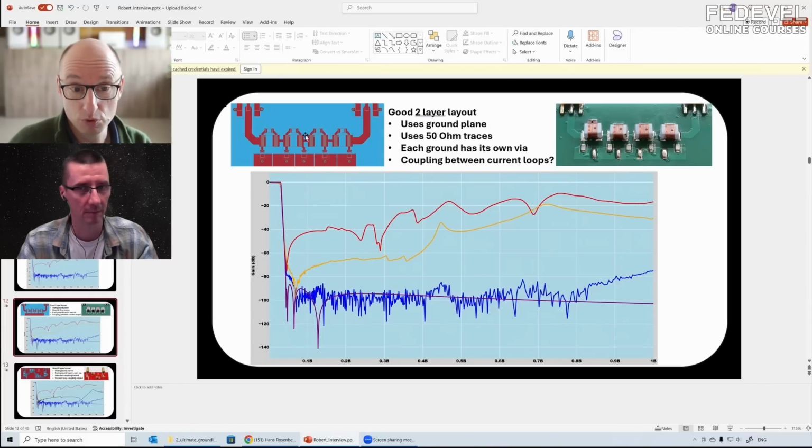I wanted to get to the root cause. So I removed these right 3 sections and just looked at the response with these 3 parts: this capacitor, this inductor, and that capacitor. I compared it to the simulation, and there was a perfect correlation. So I thought, okay, that part works. Then I placed this capacitor, and it suddenly started deviating like crazy from the simulation. I mean, a huge difference. So I thought, what the heck is going on?